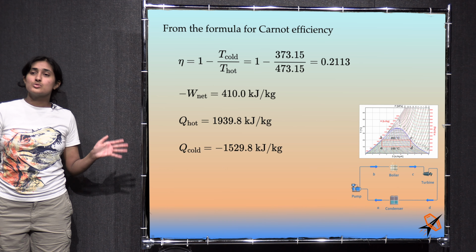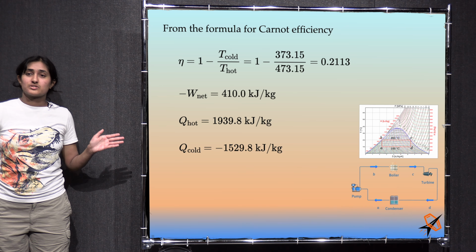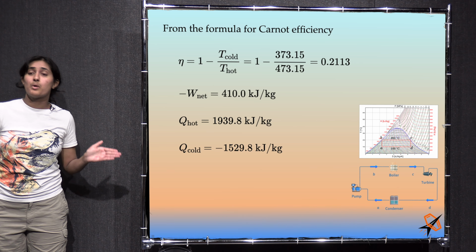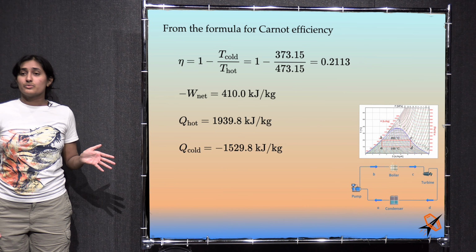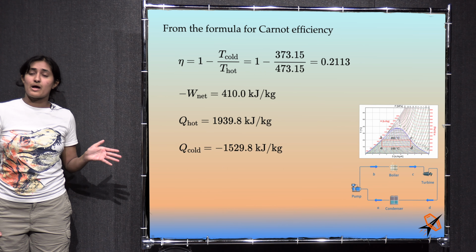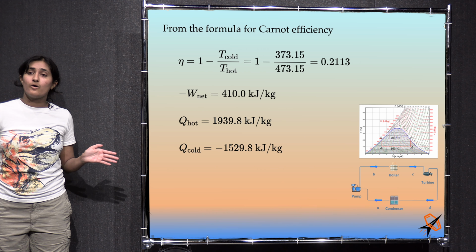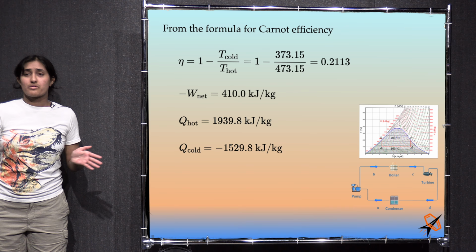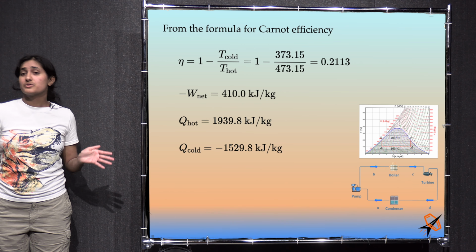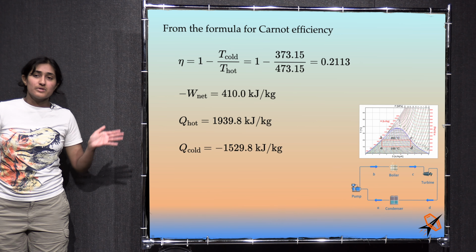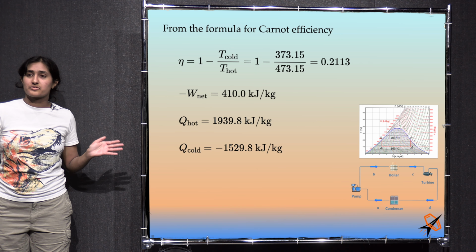We have now demonstrated two different Carnot engines, one where each step was a closed system and air was the working fluid, and one where each step was an open, steady-state system with water as the working fluid. As mentioned, we will use the first one as the basis for air standard power cycles. The second one will be used as the basis of the Rankine cycle, which is the basis for all of the big steam-generating power plants, whether they are powered by coal, by natural gas, or by nuclear energy. So what are the engineering problems with the steam Carnot cycle? We will let you ponder those for a while, and we will move on to other things.